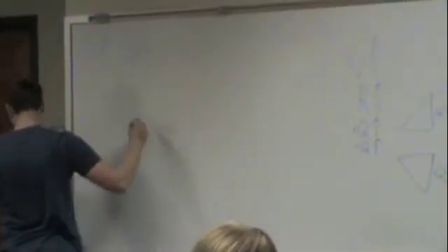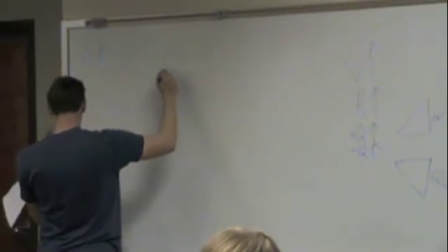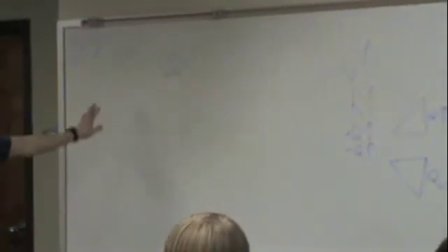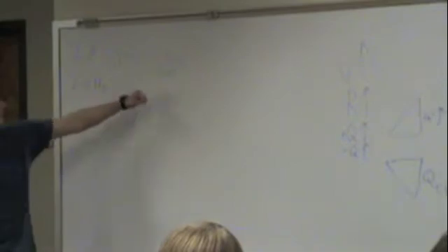For a control system whose open loop gain is G of S, remember G of S is the open loop gain, always and forever, equals 20 over S plus 10 to the third. This one problem is really easy. Okay, so for the open loop given there, what is the approximate break frequency in hertz? No, in hertz. What is the approximate break frequency given a pole?